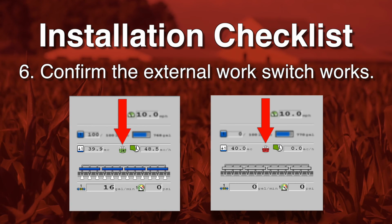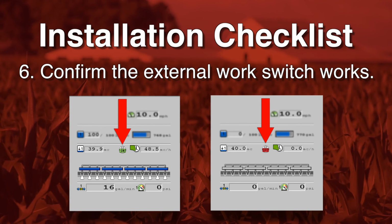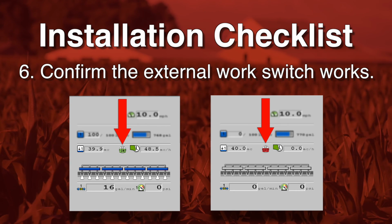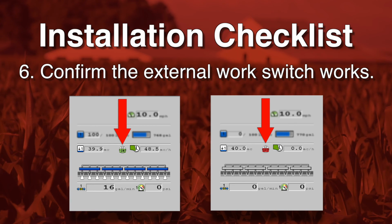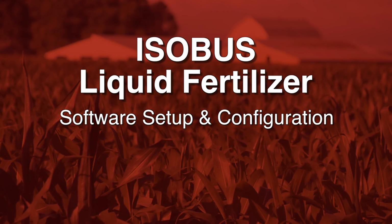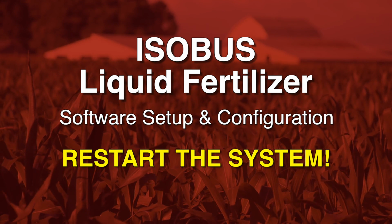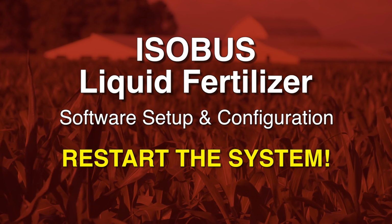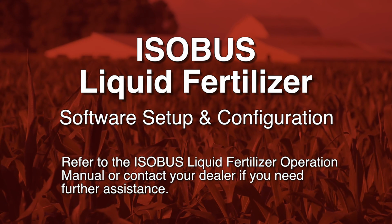Finally, if a foot switch or external work switch is installed, verify that the switch is validating correctly on the universal terminal. Sections should be turned on and off with the engagement of this switch. This completes the software setup and configuration of the ISOBUS liquid fertilizer system. You need to restart the system for the setup and configuration settings to now take effect. Refer to your operation manual or contact your dealer if you need further assistance.